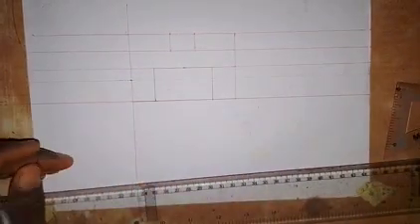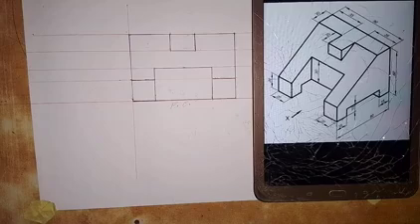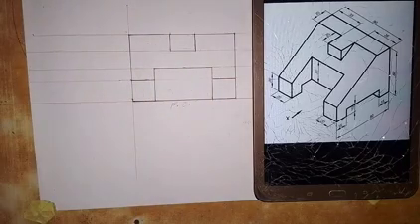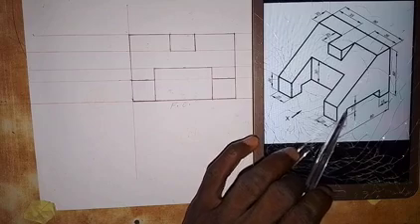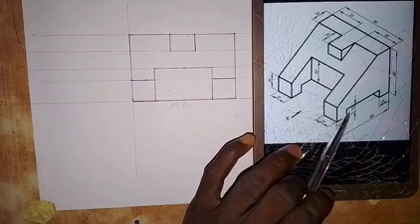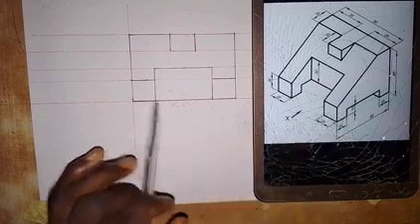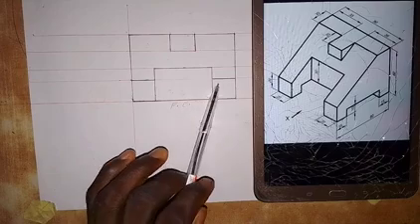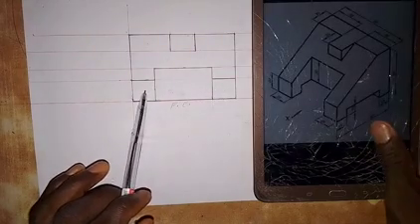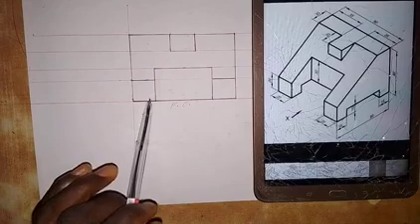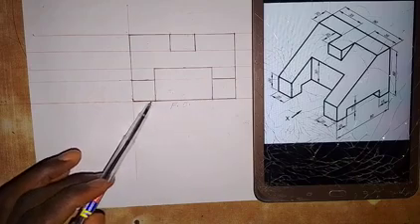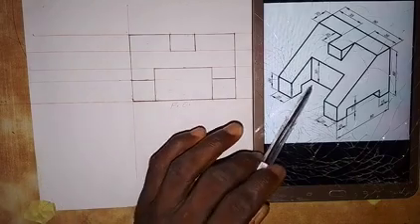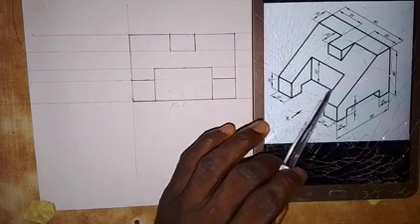I'll pause the video and bring out the shape. I've brought out the shape of the front elevation, but there's something that we need to put here. We have a cut under here, and the distance from here to here is 10 millimeters. It will be hidden from us in the front elevation for this part and also for this part that we have here. Even this line is not supposed to be a thick line, because this is at the same level with this.